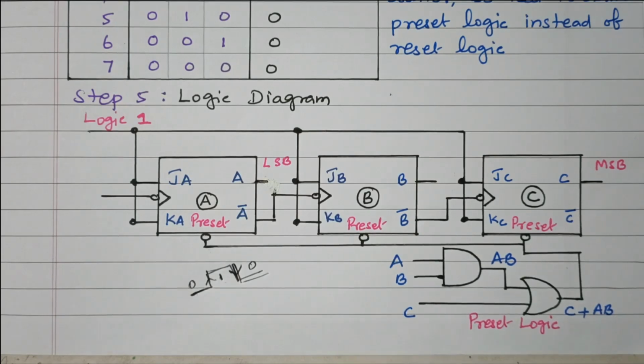So in this video we discussed the design of ripple counter using the state diagram. In the state diagram, 5 states are there, and also we have 3 digits, and it's coming under down counter. So we discussed, based on the condition, we decided 3 flip-flops are needed. Then we discussed the truth table. For the given 5 states the output is 1, remaining states are 0. Based on that, we obtained the logical expression for preset because of down count. That preset is implemented in the logic gate. We are using JK flip-flop.